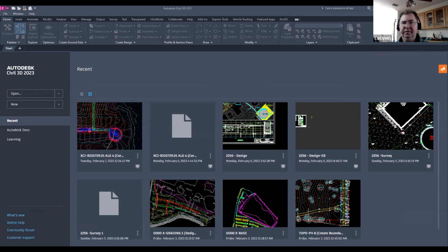And now I have my corridor information. This is going to be my road 1 corridor. And then down here, I've got phase 2. Let's see what actual region this is right through here. I can probably come back and then use my splitter again to move that back over.